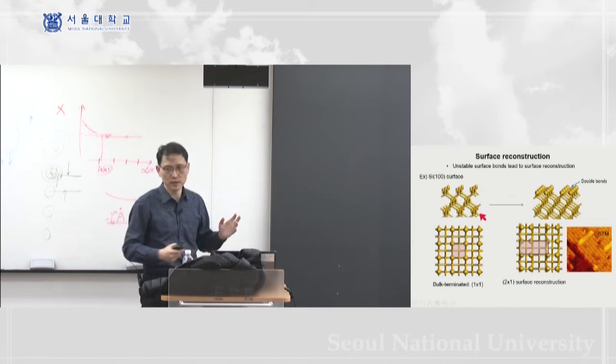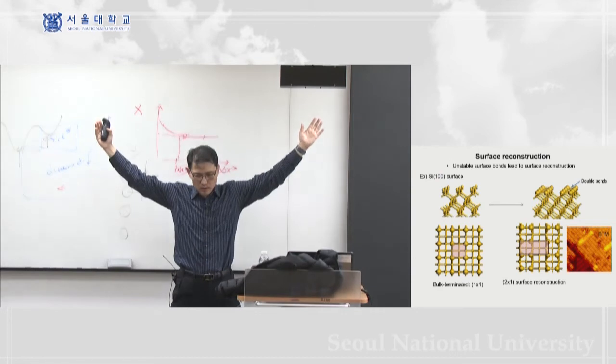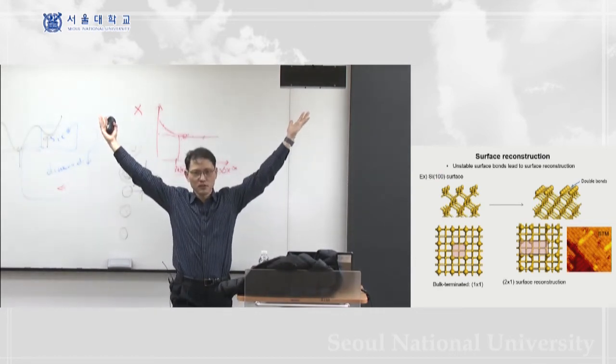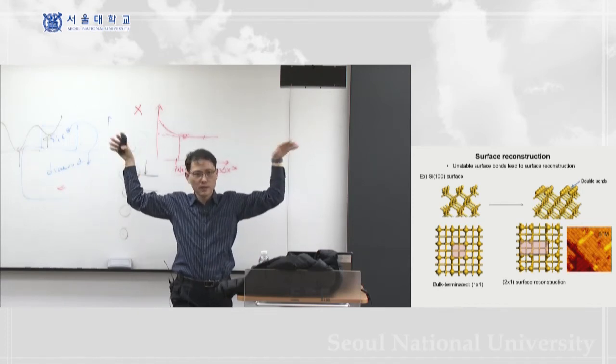All right, silicon usually has full bonding. It has 4 tetrahedral bonding, like up here. This is a 4 silicon bonding. And in the 100 surface, you have cut these 2 bonding. It's a dangling bond, all right?